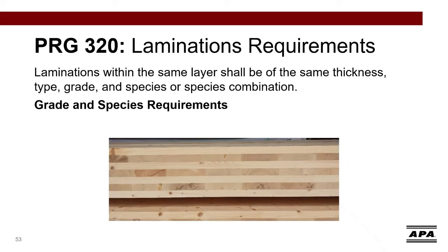Laminations within the same layer shall be the same thickness, type, grade, and species or species combination. Note that this is only true for laminations in the same layer. Laminations in different layers may be different than the layers above or below.